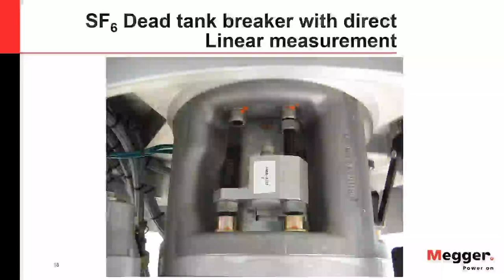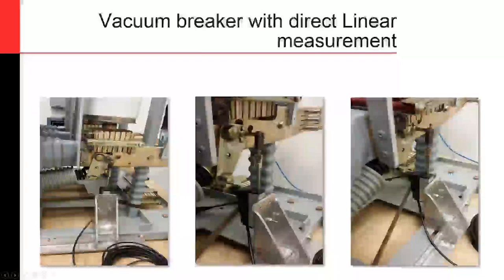And so these hook up, and that actual mechanism is connected directly to the interrupter. So as that mechanism drives in and out, it drives that interrupter in and out, and we're hooking directly to that and measuring the exact stroke of that interrupter and the exact velocities over travel and all the related parameters that go along with the stroke there.